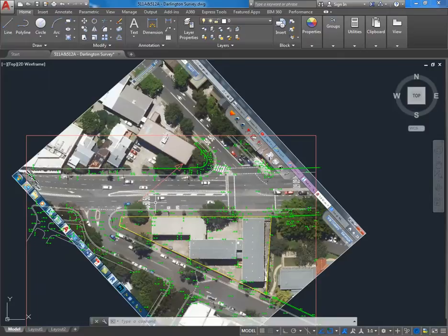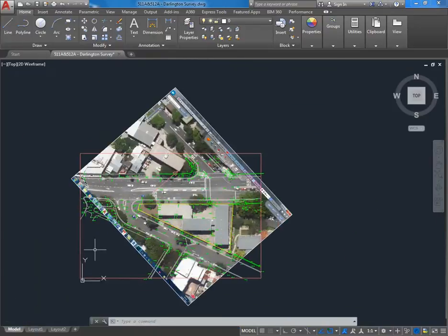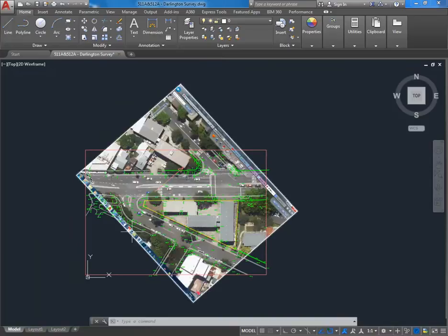And then you can simply reload this file in Revit, and when you're making your subregions in your topo surfaces, you can simply pick those lines, because you'll probably have many subregions with the edges touching, and it's much easier just to pick the lines you've drawn in AutoCAD instead of drawing all these subregions individually in Revit. So it'll help you a lot with that, and also hopefully we'll get you used to having linked files in Revit, and that's the next thing I'm going to show you.